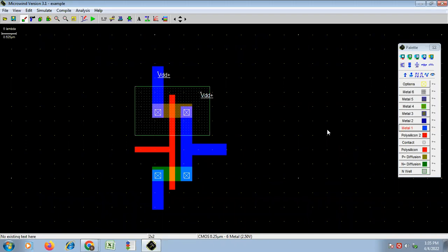Yes, sir. Okay, fine. So here from this panel VDD supply, you are taking VDD and placing it over here. Then again to the NWELL also. Now you will think, okay, for PMOS we are giving this NWELL. Now about NMOS, where is a PWELL? Right? Where is a PWELL? So the answer is, the entire background itself is a PWELL in case of NMOS.